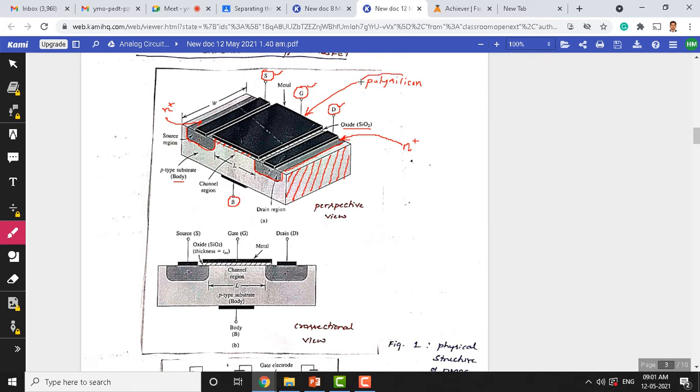So that's why this silicon as a conductor is nothing but polysilicon. The silicon, which is a poly, is made in the form of polycrystalline silicon. This behaves like a conductor. So therefore we use it in place of metal, okay, so the polysilicon acts like a metal here. So we can attach a terminal, an electrode, to this. So this is the 3 terminal, the 3D view of the MOSFET here. Okay, so go through this. If you have any questions you can ask related to this.